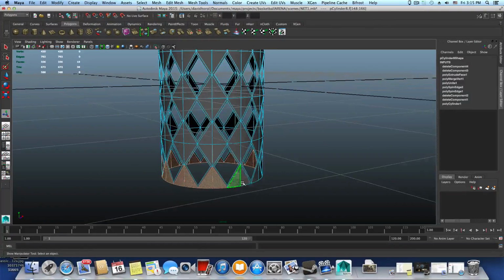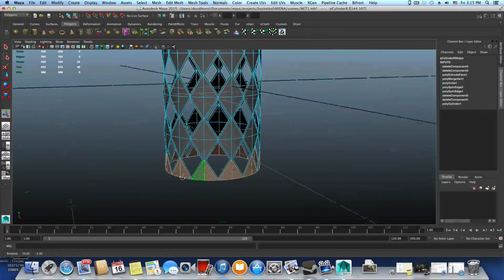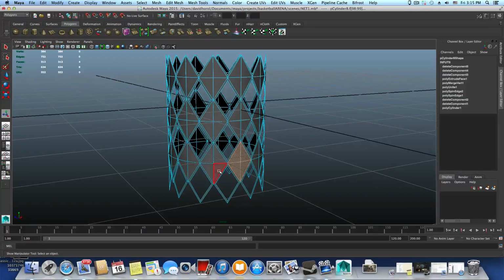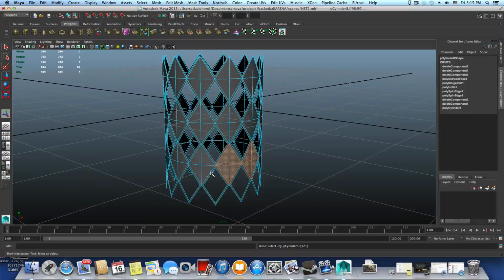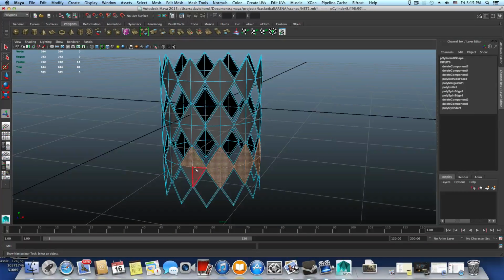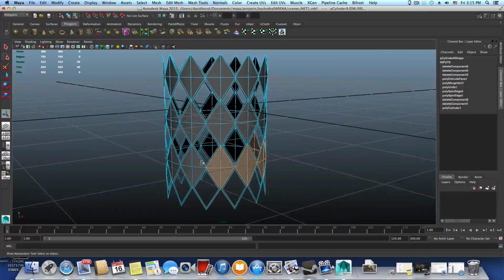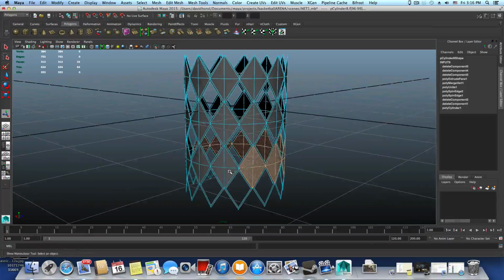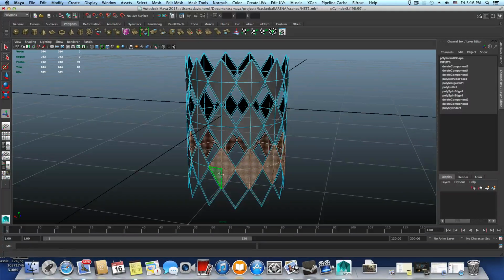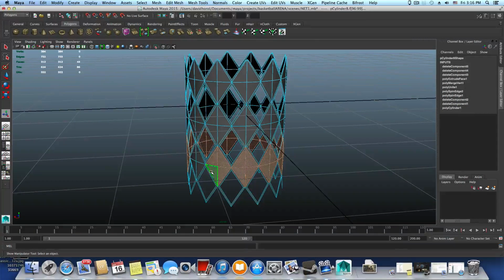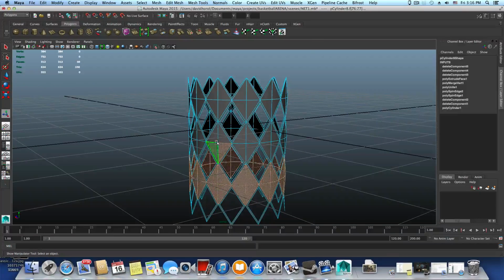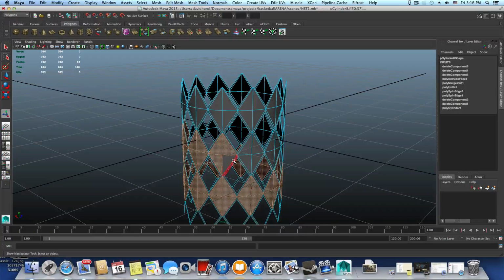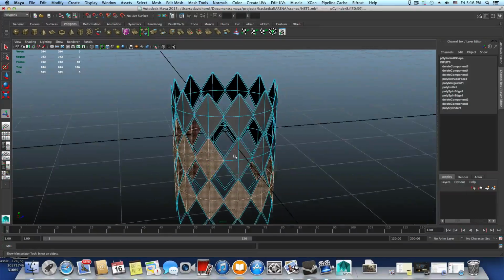So let's delete those, and I'm gonna grab those faces. And this is a little bit funny, but I do need to extrude those also, even though they already have a frame that belongs to the other holes here. Okay, and yeah, we need them. We need to extrude those faces as well. The ones that we already extruded, basically we deleted them. So those that are left over here look like they were extruded, but they haven't been extruded. So be aware of this.